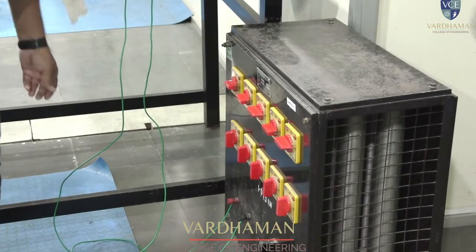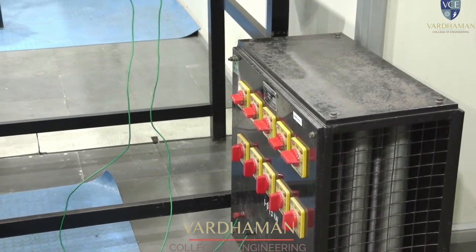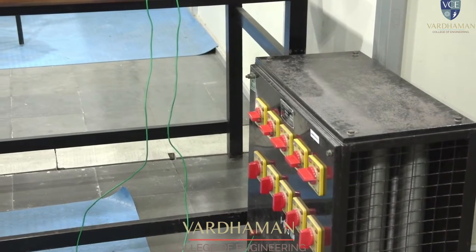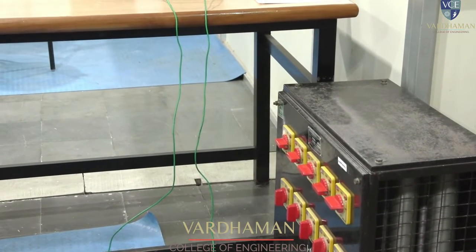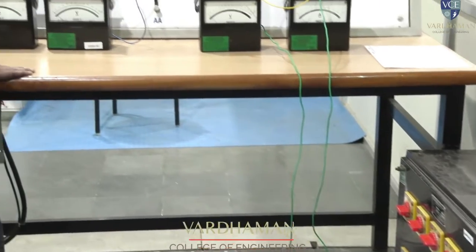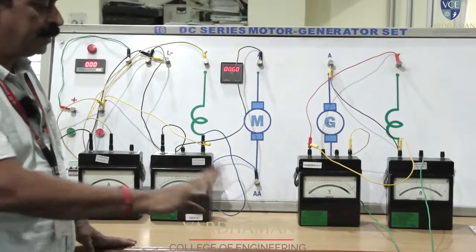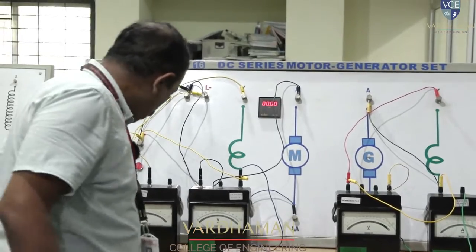A DC generator should never be started without load. That is the only precaution we need to take. If the load is at zero position and you switch on the equipment, it will rotate at the highest speed. That is dangerous for the motor. It will damage itself with its own speed. So that's the reason I switched on the load.